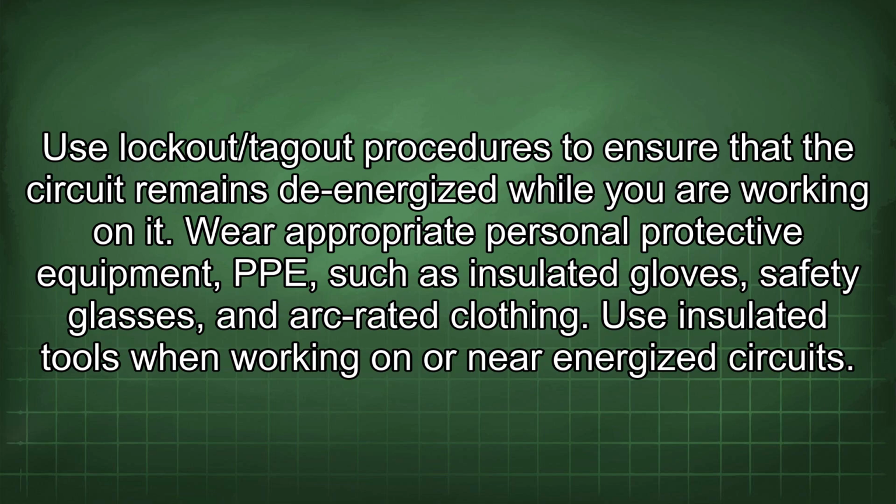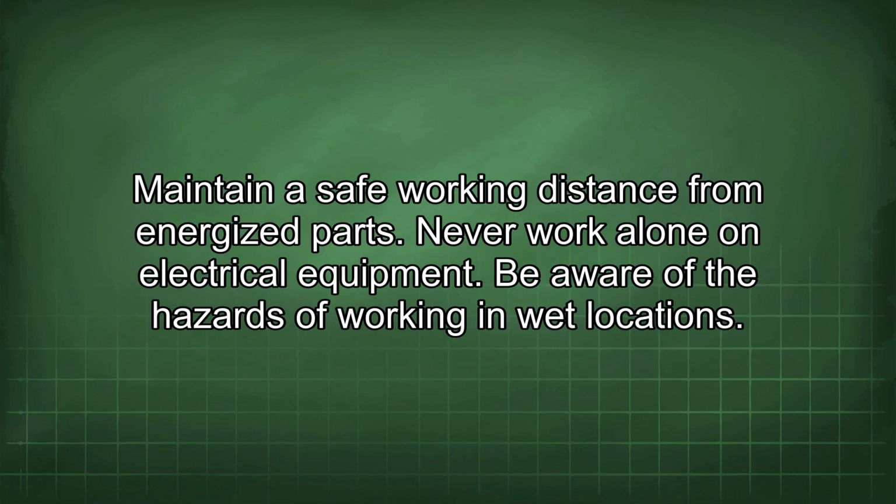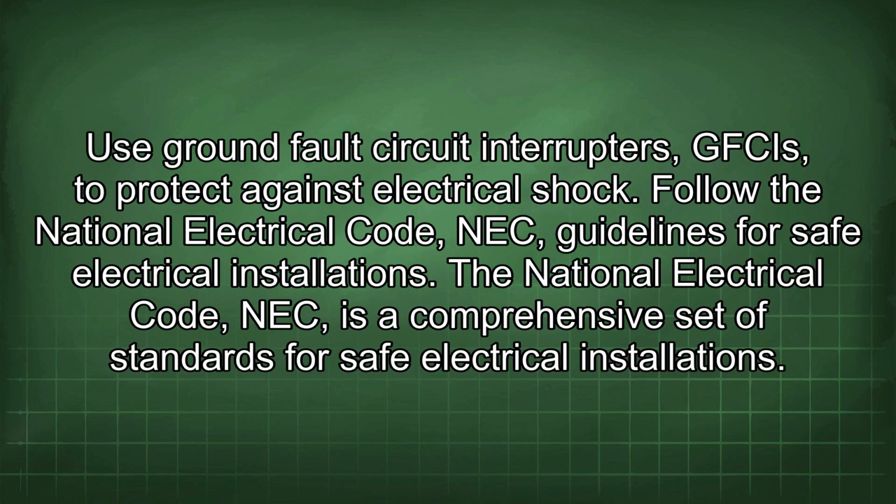Use insulated tools when working on or near energized circuits. Maintain a safe working distance from energized parts. Never work alone on electrical equipment. Be aware of the hazards of working in wet locations. Use ground fault circuit interrupters, GFCIs, to protect against electrical shock. Follow the National Electrical Code (NEC) guidelines for safe electrical installations.